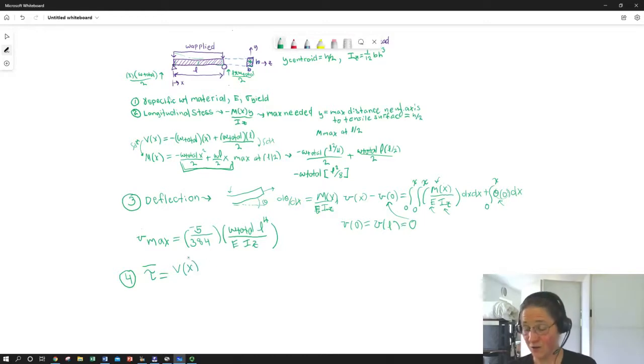It's going to be our shear force, which is why it's really important to know where this was a maximum. Now I'm going to write this out from the basic equation. I'm going to take a step back. So shear stress, average shear stress times the width of the plane that we're considering, which in our case is b.